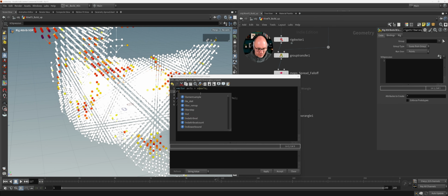And now we want to create the float angle. And this is where we want to bring in the control or the animation from our falloff attributes that our MOPs falloff creates. And we can do this with a channel ramp function. So let's bring in a channel ramp function because then we can map the rotation of our objects on the value of our ramp. So our ramp creates values from 0 to 1, and then we can specify how much rotation we want on this 0 to 1 range. It will make more sense in a moment.